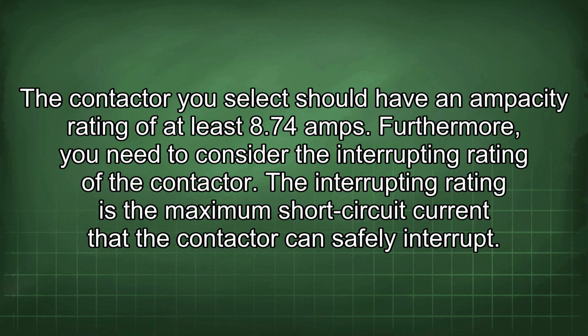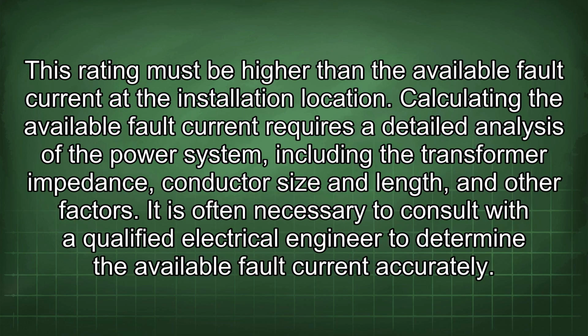Furthermore, you need to consider the interrupting rating of the contactor. The interrupting rating is the maximum short circuit current that the contactor can safely interrupt. This rating must be higher than the available fault current at the installation location.